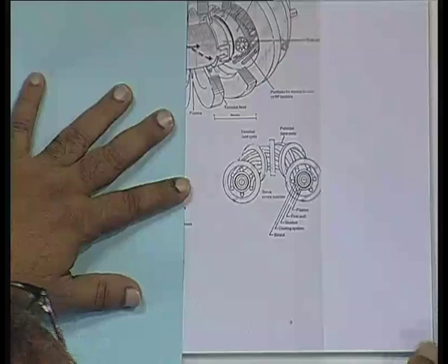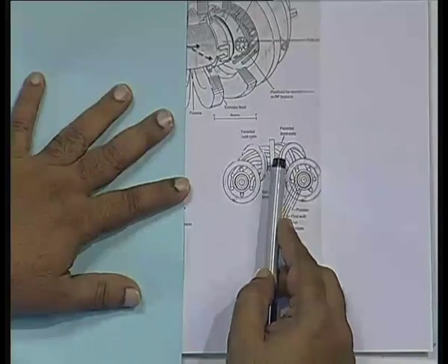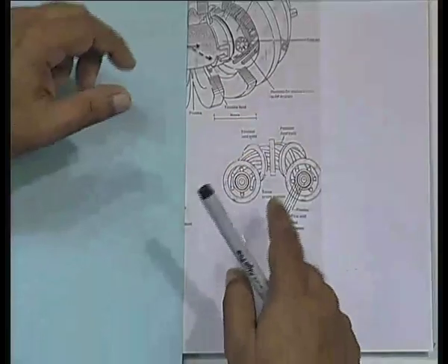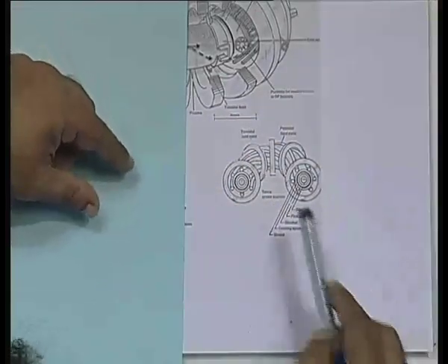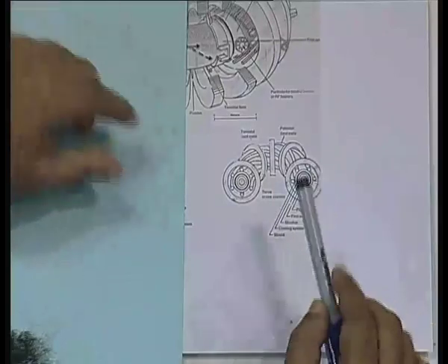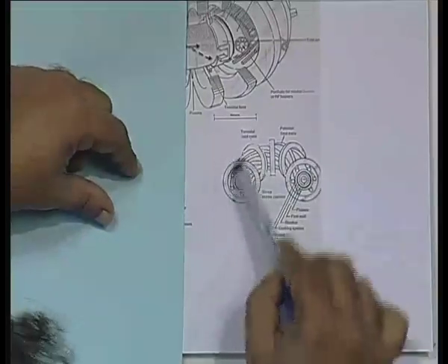Why do we need to have them twisted? Because if you have a high amount of current flowing through, they will try to fly off. So, unless you twist it, there is no structural stability. So, you have to have a bit of twisting around it. So, there are two windings really, the toroidal windings and the poloidal windings.